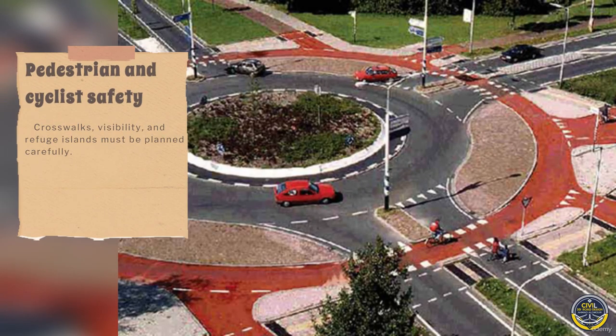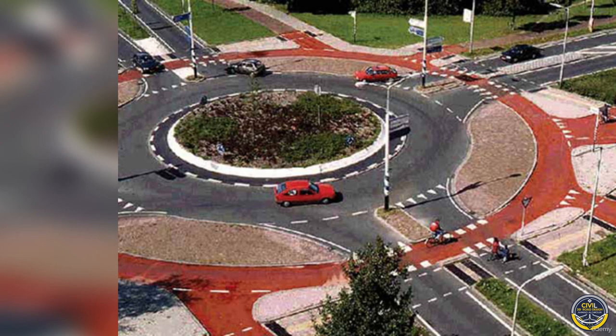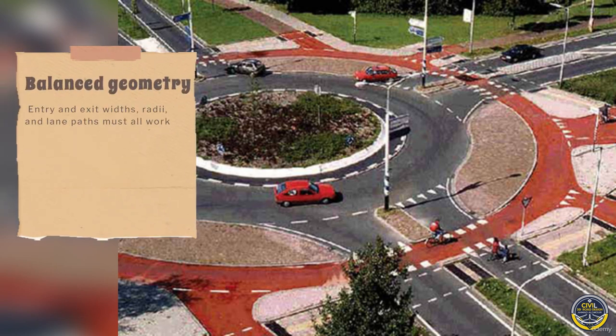Pedestrian and cyclist safety. Crosswalks, visibility, and refuge islands must be planned carefully. Balanced geometry. Entry and exit widths, radii, and lane widths must all work together. These principles ensure a roundabout performs well, remains safe, and meets real-world traffic needs.